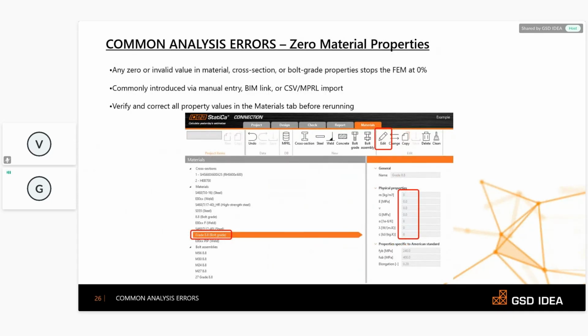Now, I don't know if you have noticed this, but these days this is the most common source of error. I'm not limiting this to connection application, but I'd like to take it also to the concrete application, be it 2D or especially not much in 3D, but when it comes to connection and 2D, I've noticed this quite often, that the physical properties of the materials are marked as null, or are given a null value.